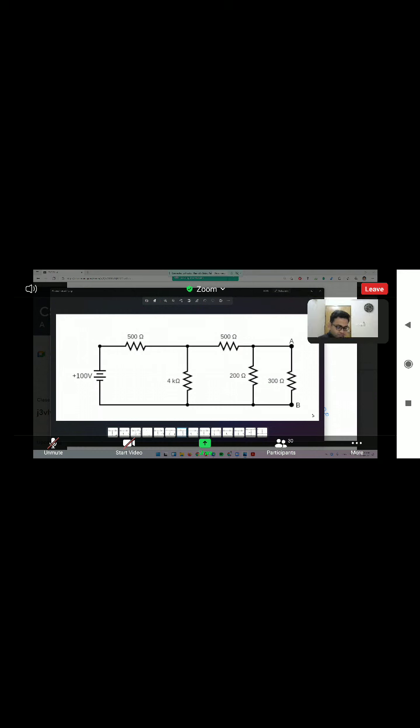Okay. So if it is the RT, then it is very easy to find the total current, because our total current I is equal to 100 divided by RT, 1095.7446. Yes, sir. So the total current should be 0.0912. Is it the same to others? Total current? Yes, sir. Very close.